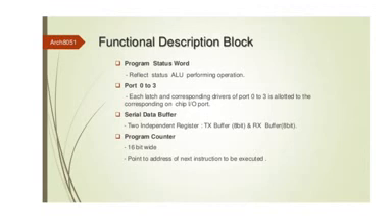Next, the program counter. This program counter is a 16-bit register. DPTR is a 16-bit register, and the program counter is a 16-bit register. The two timers T0 and T1 are 16-bit timers and counters. Apart from these, almost all the registers are 8-bit. The program counter is used to hold the address of the next instruction to be fetched. Generally, the PC is automatically incremented to point to the next instruction in the program sequence after the execution of the current instruction.